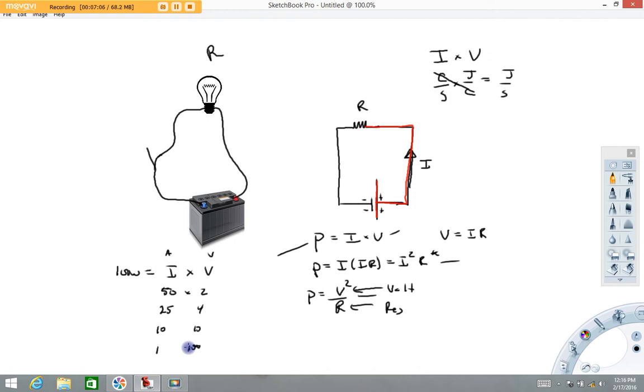It's very important to realize, though, that as a rule of thumb, high current means high heat, means less efficiency. Heat is the natural enemy to all electrical circuits. So in this example that I went through, this would be the most efficient circuit. It's always advantageous to transmit power at as high a voltage and lowest current as you possibly can. And I'm going to make more videos talking about why later on.